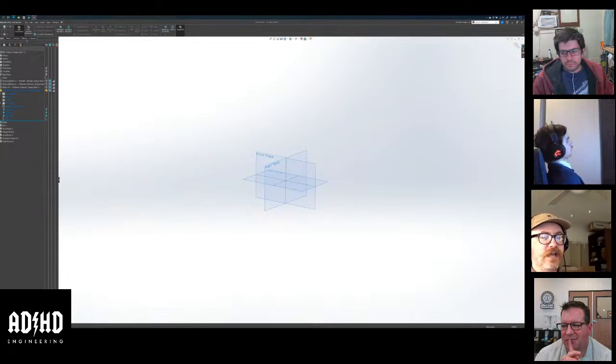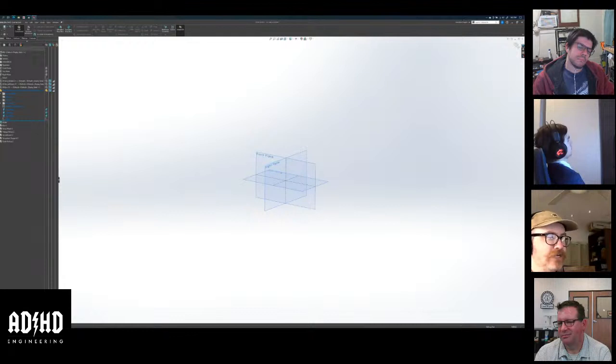Now I have the sketch geometry on a very robust plane, and I've defined how far to distance it, instead of creating a plane specifically for sketching on and then doing an extrude from that position. So you're making your breadcrumbs, your digital trail of data. I think it's more logical for me, but maybe not for everybody.